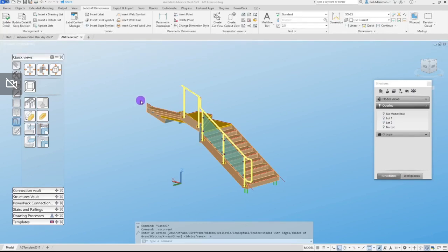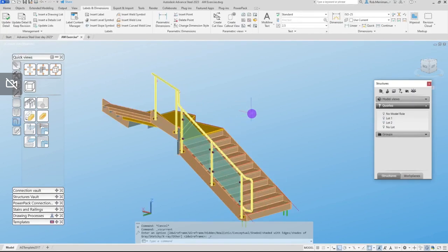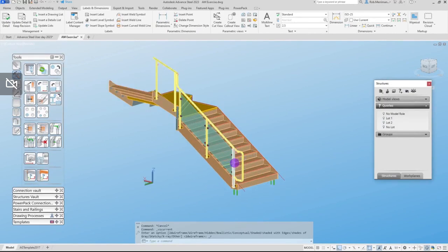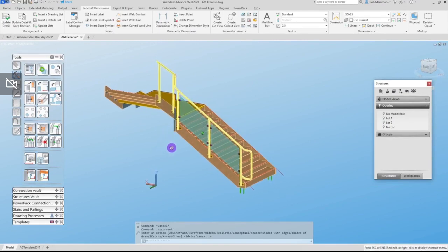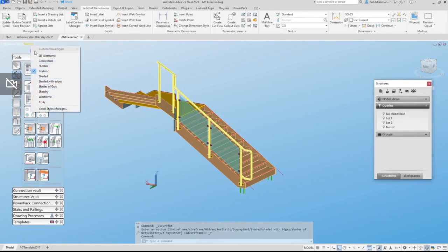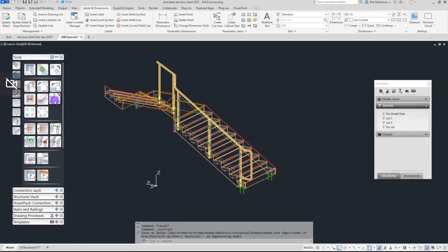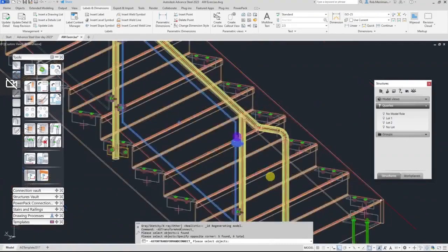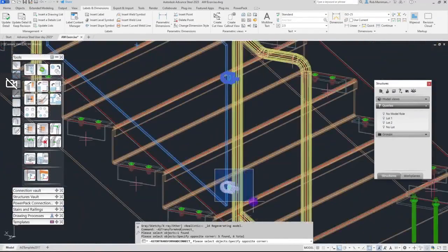Let's see that. So we've got the model here, quite familiar with it again, and you've got panels. We're going to use Copy with Adjustment. We're going to go in here and look at these panels. The lower panel is the same as the top rail, but it's going to be rotated. So we're going to start Copy with Adjustment. I'm going to come in here and copy the panel. We're going to select those glass clamps, so just little windows to do that.